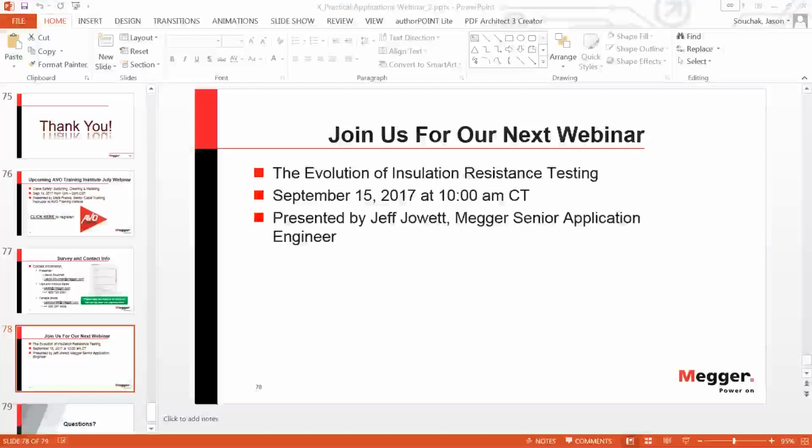grow through the insulation. And if you look at the growth rates, which are about 10 millimeter per hour, and you look at the typical insulation thicknesses for medium voltage cable, then you can see why an hour period is a good time to accomplish this. And there's some more information about this in our previous webinar about VLF testing.